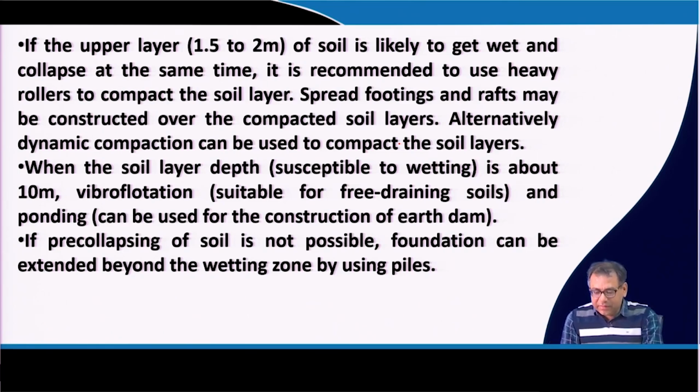Then spread footings and raft may be constructed over that compacted soil. Alternatively, we can use dynamic compaction to compact this soil layer. These ground improvement techniques, dynamic compaction, vibro flotation, are all common ground improvement techniques, and those are taught in your ground improvement course.